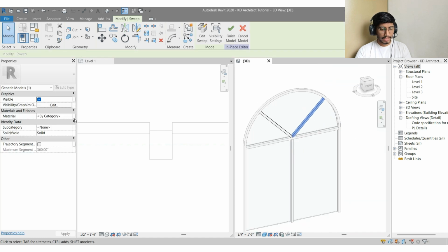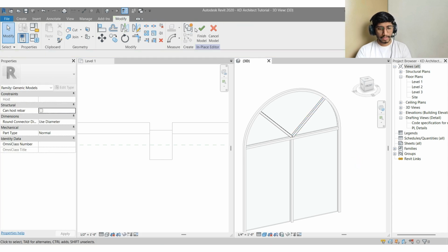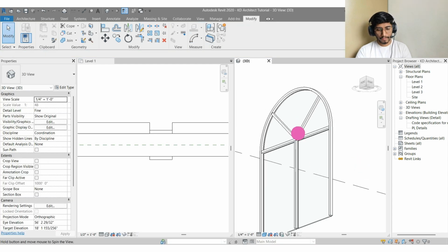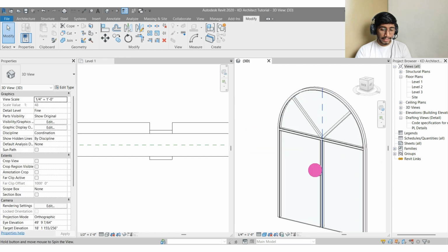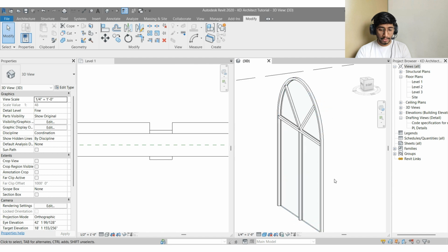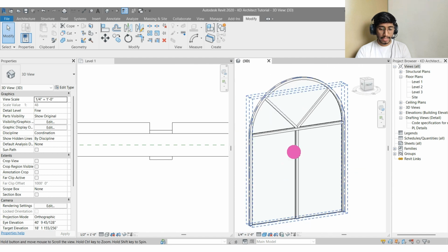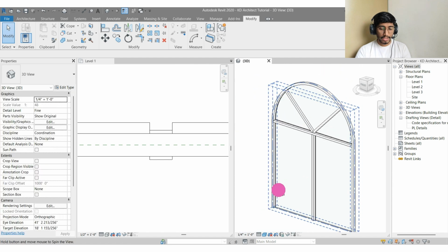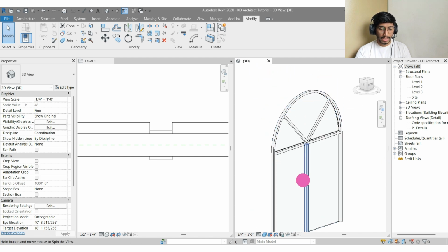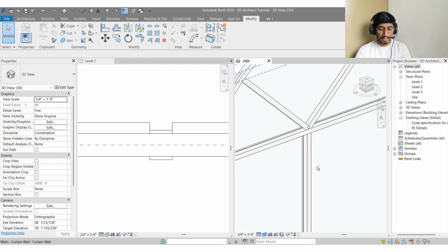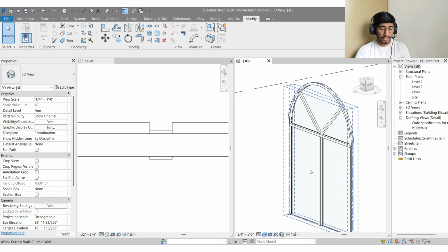Now again assign the same material over here. So just Control V over here. So we have added two mullions. This is the process by which you can add the diagonal mullions. You can create the model in place like this way. This is one of the ways to create diagonal mullions. You can assign the same materials, so it will look like a mullion in the diagonal direction. So this is the method and process to create a diagonal mullion in the curtain wall.